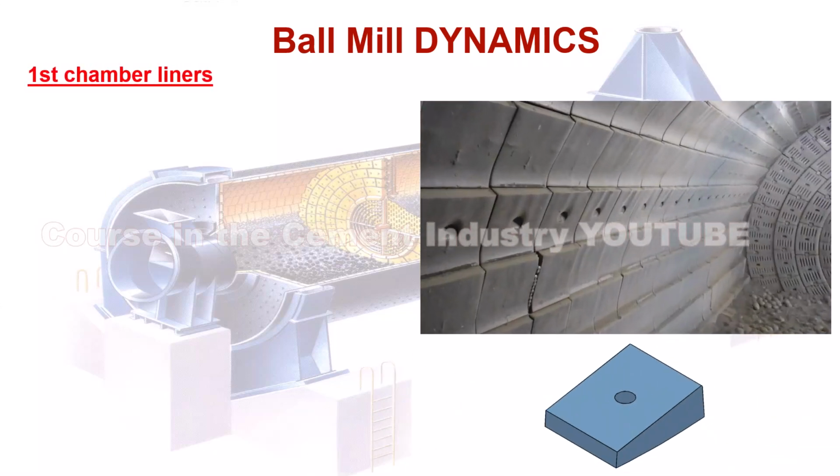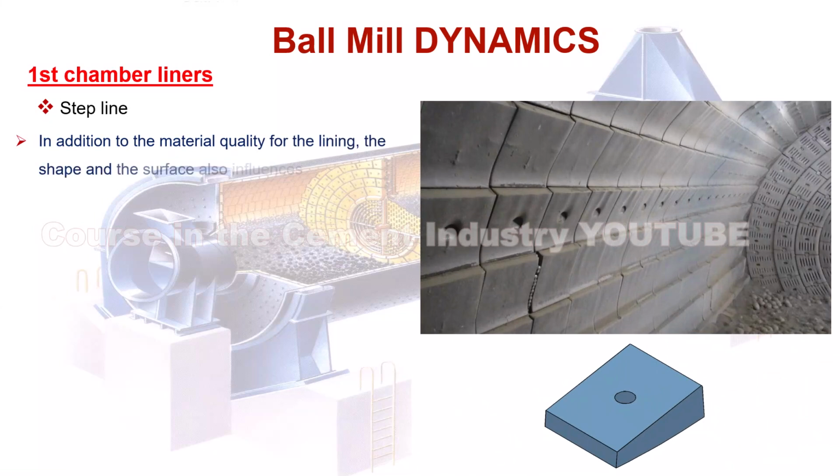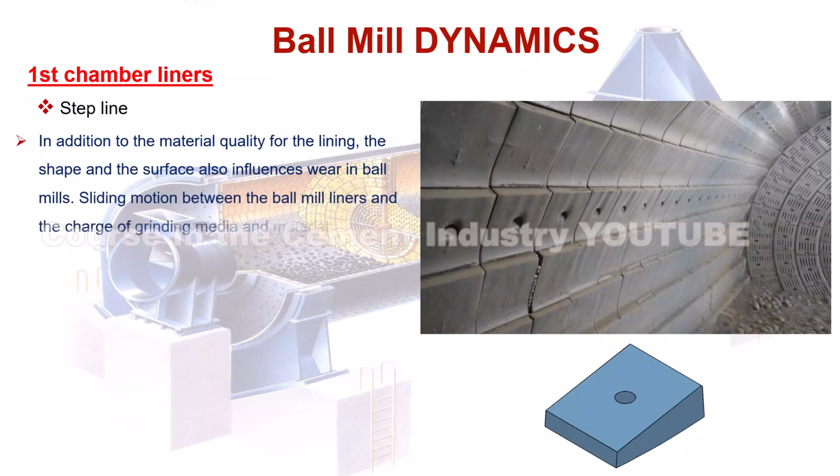This figure shows step liner. In addition to the material quality for the lining, the shape and the surface also influence wear in ball mills. Sliding motion between the ball mill liners and the charge of grinding media and material is, to a very great extent, responsible for wear on lining plates on the mill shell.